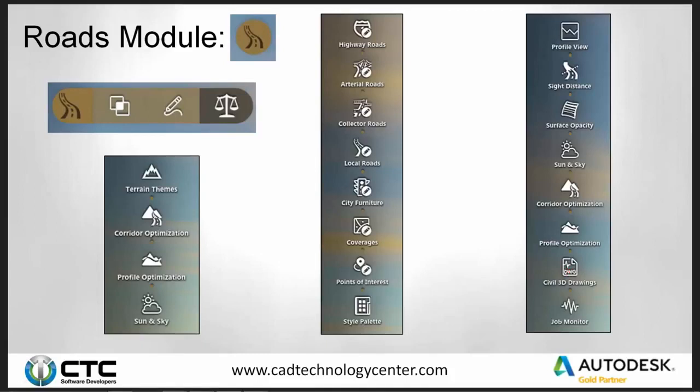It will use templates that you define, and so I can have a D-size sheet with 40 scale, and it will determine how many sheets it needs. It's nothing more than view frame groups in Civil 3D, but it does it in Infraworks. So I can create quick sheets right away and have it build P&P sheets for me in a couple of minutes without ever having to go into Civil.